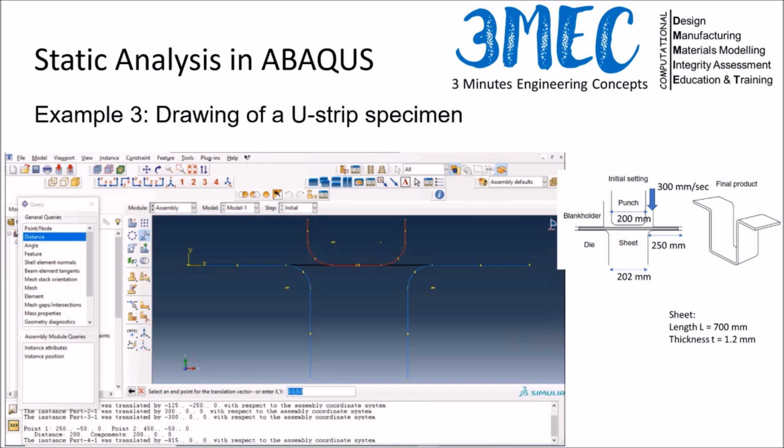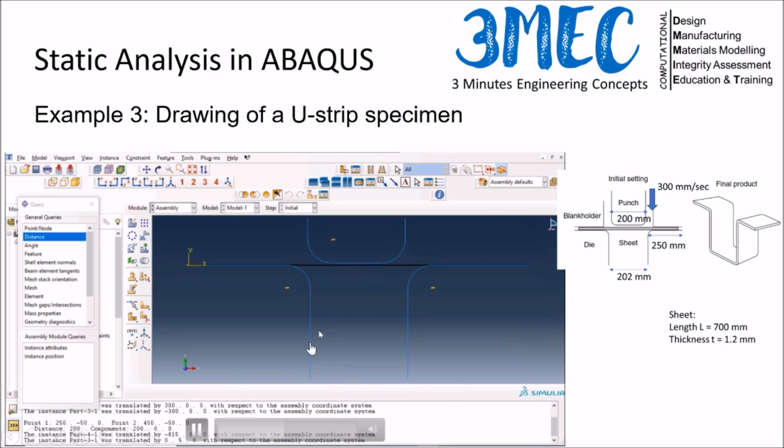So I will move it to, let's say, 10 millimeters. If I'm happy or not, maybe not. So it's too much. It will take a long time. So I'm trying to bring it much nearer, and I used 5 millimeters. Maybe I can use 1 or 2 millimeters as well. It's just to reduce the computational time, because during the travel we don't see any benefit until it touches the sheet. Okay, once I have done that, I can go to the mesh module and I can mesh parts.